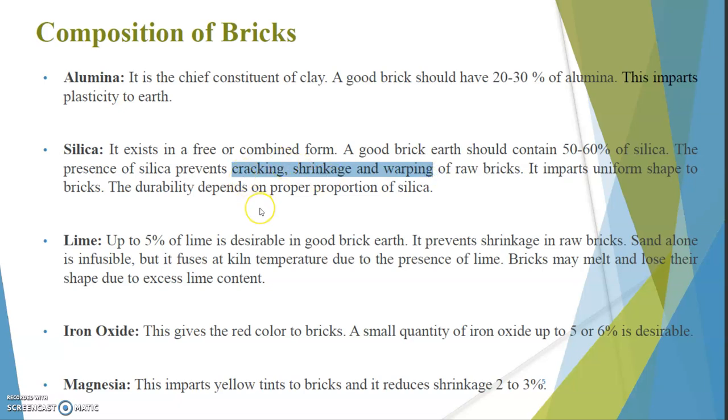Cracking, in the sense, of course, we know if the mass of the brick doesn't have enough silica, it may not have a uniform structure. When we subject the mass of clay to the process of making brick, that is molding, drying, and burning, during the drying process, due to insufficient silica, cracking may happen.